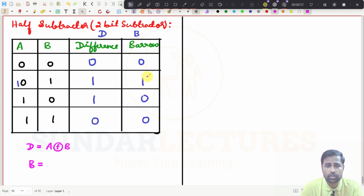See, you don't have any ones here. Only you have one here. So what you do? You straight away go here. What is this value? This is A, right? In A, you are giving input as 0 and in B you are giving input as 1. So what should be the output here? If you have a single 1 in the output, then it will be A bar and then B simply in SOP functions. If it is a POS, then it will be what? A plus B bar. Anyhow, I'm not going very deep into that. So this is the output equation.